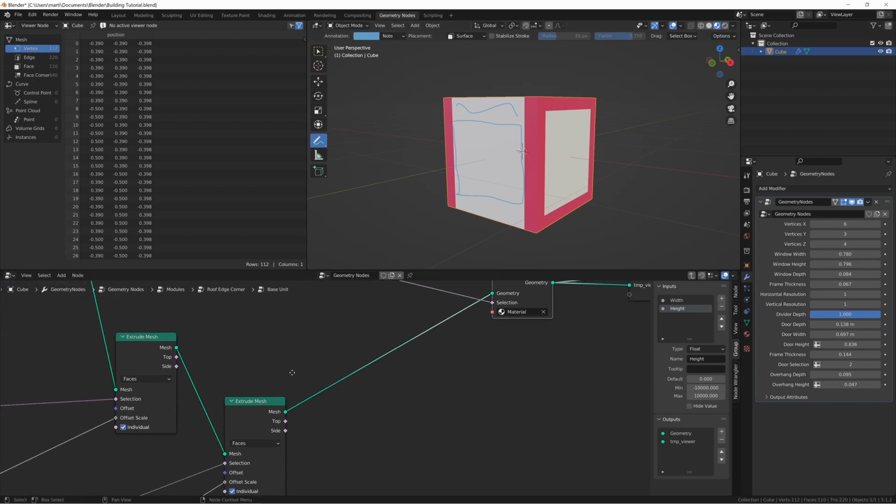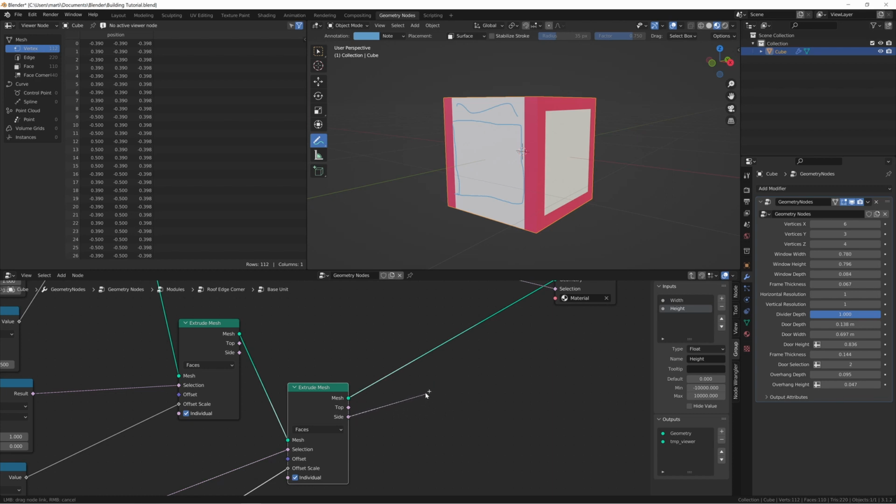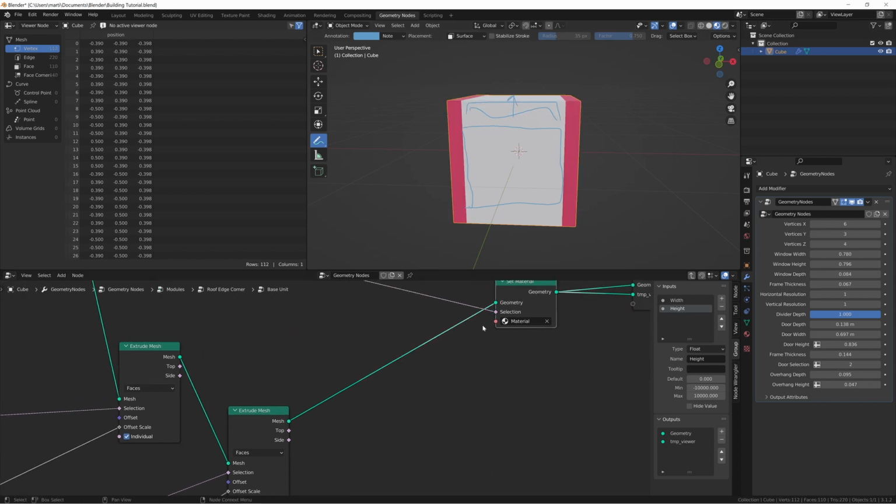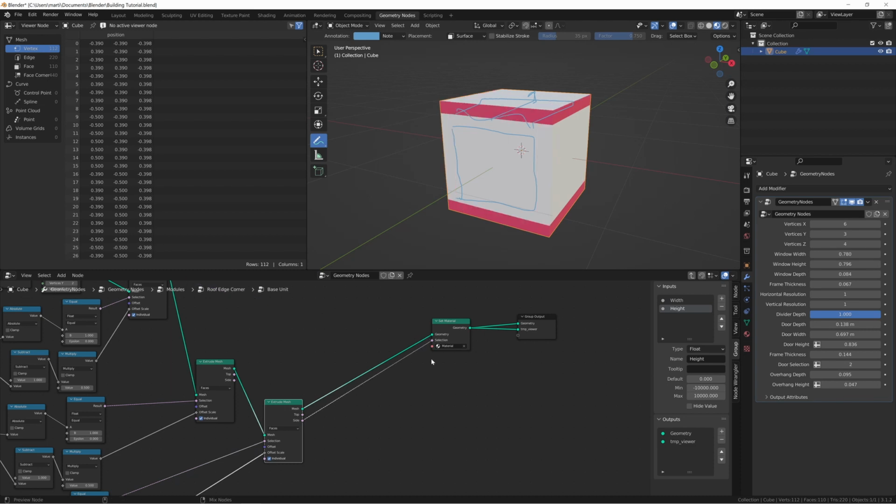And we'll do that with the extrude mesh sides from the last one, the one that extrudes the height, because once we have all of the stuff along the sides, from a top-down view it's the right size and everything, but we're just extruding it up like this, so we can use the sides to build in the extrusion selection right there. I'll just show you. If we just use this selection, it does an opposite thing. If we toggle back and forth between the two, you can start to see where they're intersecting and how we can use that to our advantage. And of course, we're going to do that with Boolean math.